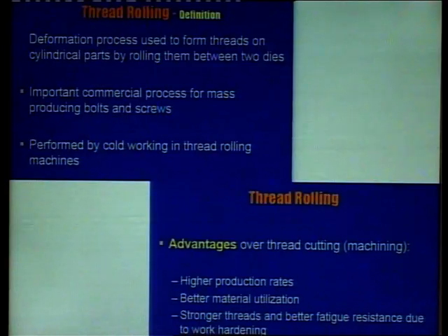Like when you make small screws, you don't cut threads by any of the processes which I said, neither by tapping, nor by lathe, nor by thread forming on the milling machine. You cut it by thread rolling. You have threaded rolls which are made to pass over the raw material, and threads are formed.